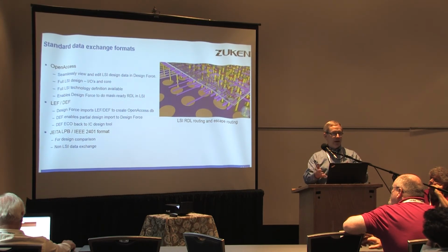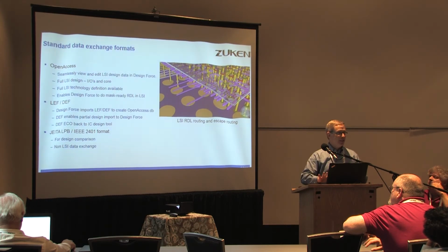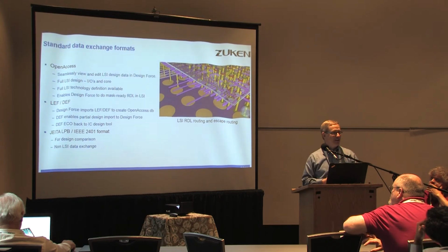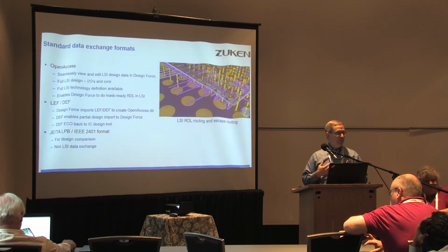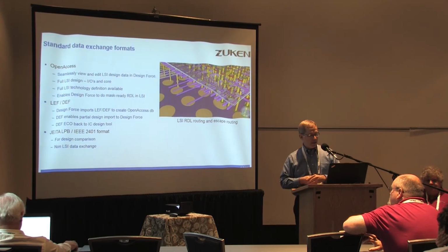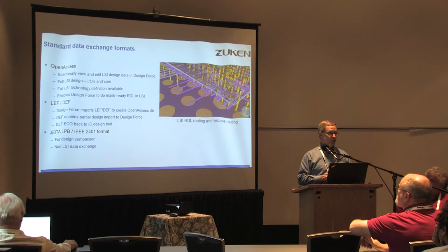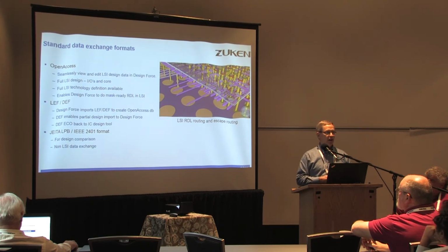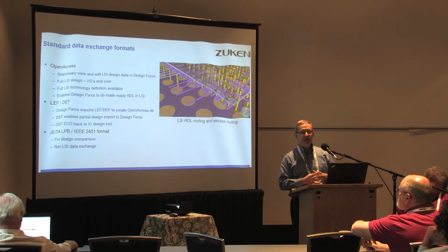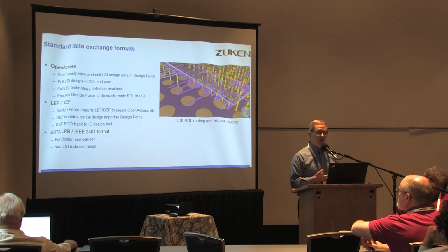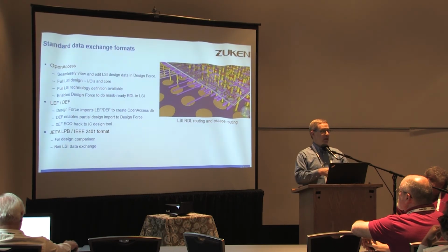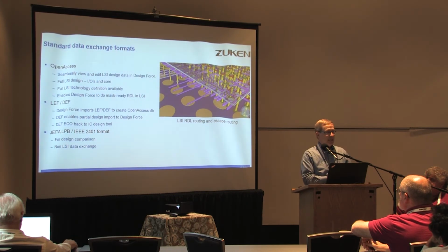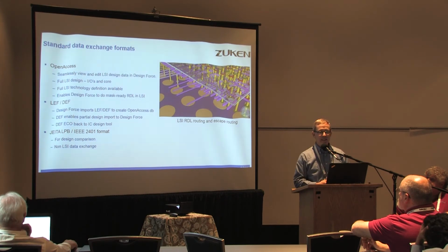With OpenAccess, we don't have a way at this point to strip that out, at least on their side, because it's not our tools. But we are able to use DEF to strip out the core. The tools that they're using have a no-core option when they export the DEF, so that we can bring in the DEF from the IC tool, and as we read the LEF/DEF, we form our own OpenAccess database to do our IC design at that point.